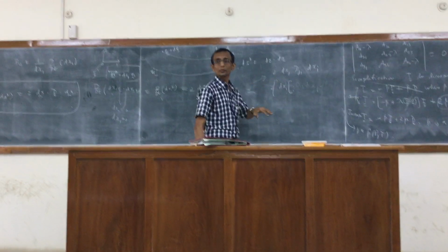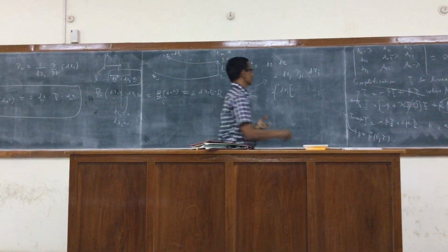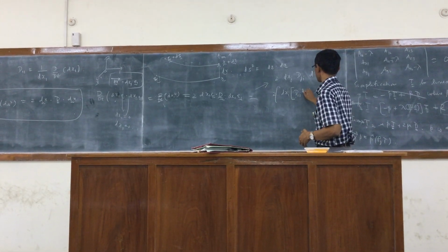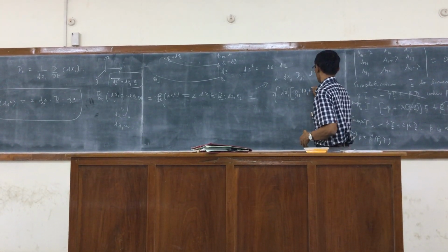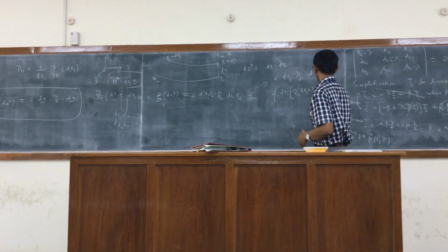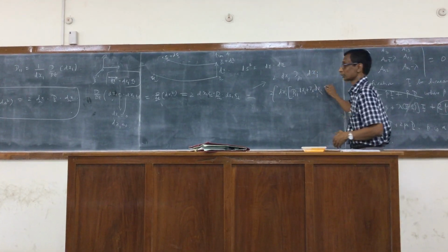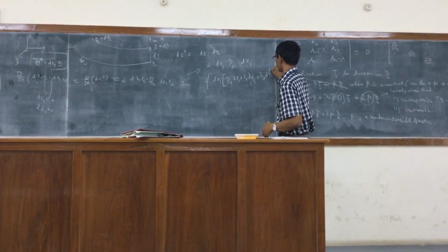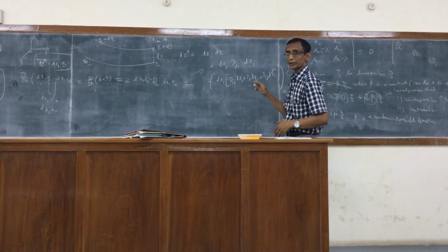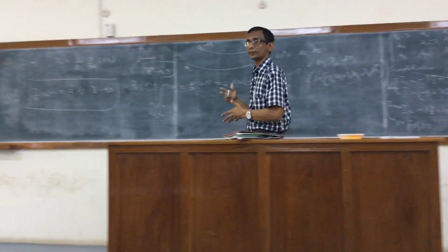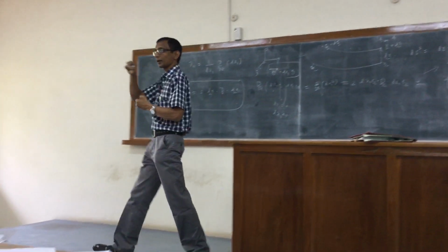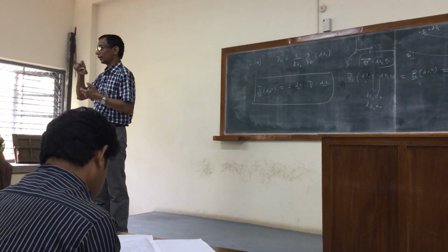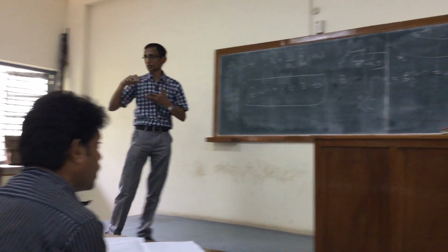Now what are the terms you said? Correct, 3 terms. This would be j equal to 1, d11 dx1 plus d12 dx2. Again this is 0, plus d13 dx3. This is also 0. For the particular dx I am considering, dx2 and dx3 are 0. It means I am considering an element of fluid oriented along the O1 direction.